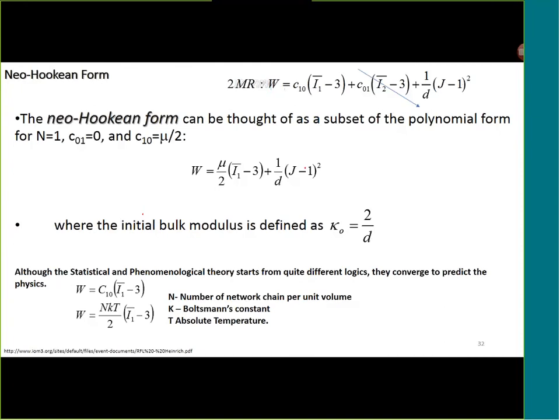Neo-Hookean is another form, or in other words a reduced form, of the 2-term Mooney-Rivlin model. If we make the second invariant 0, we get this. Again, this is one of the very simplistic material models. It requires only one material constant as an input.